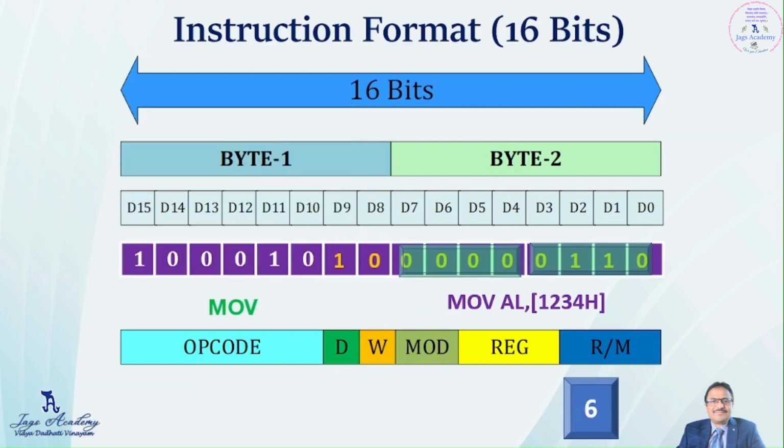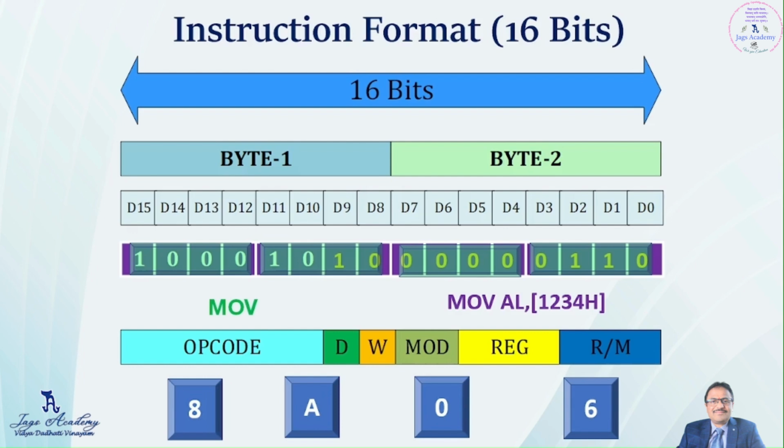Tell me. Mode bit same, right? What is changing is 111. Now tell me, instead of 6, what do you get here? What is 0111? 7. Right. Now what is the final 16-bit machine instruction? Instead of getting 8A06, you will get 8A07.